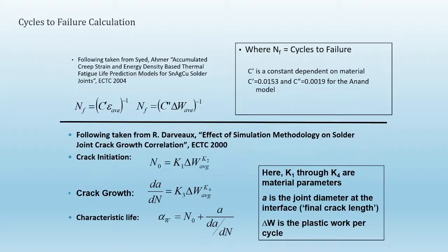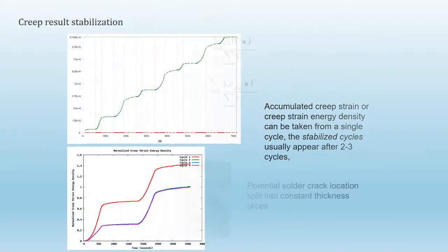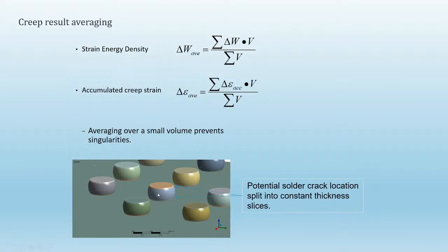If you look at the type of details that needed to be done to model just a very simple BGA, right? We need to model the solder balls and slice it up appropriately. Imagine we expand that to a whole board with potentially thousands of balls on maybe dozens of chips or more. It becomes very computationally expensive to run these simulations.